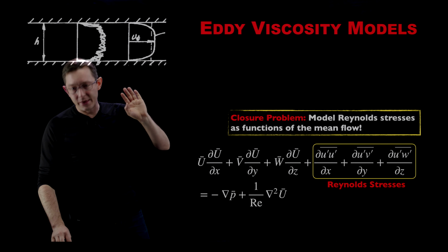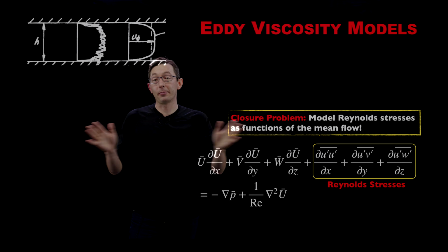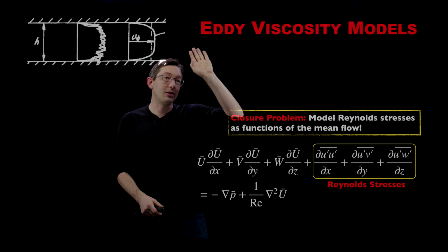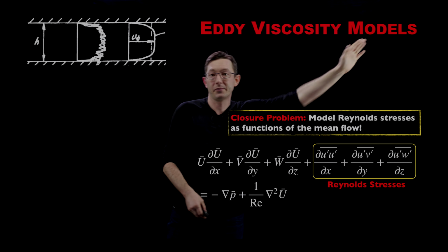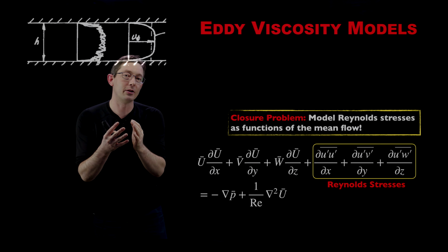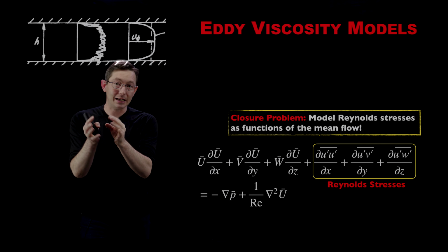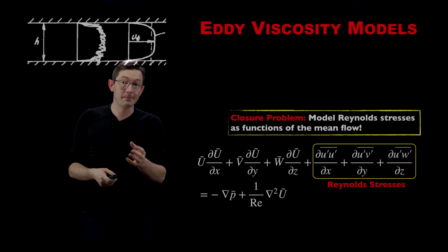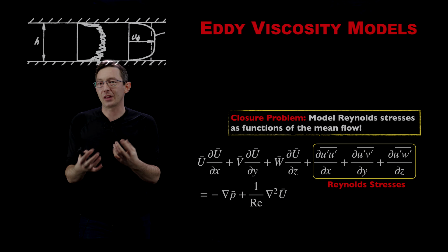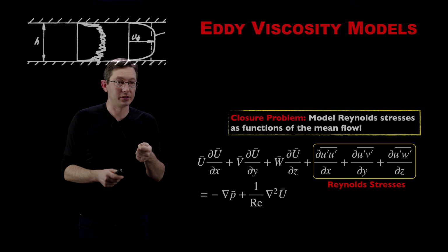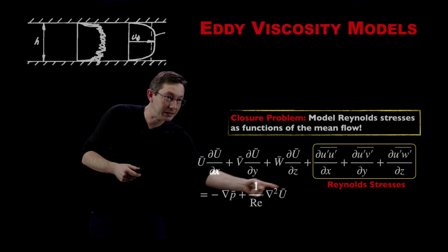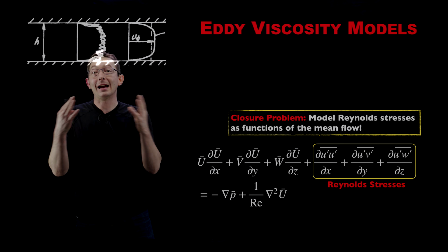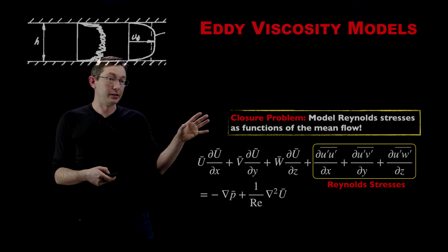And the simplest approach, actually the approach that people still take today, though this is an old approach, is called eddy viscosity modeling. So basically you're going to say that all of those tiny little turbulent scales that generate those Reynolds stresses basically act like viscosity in the Navier-Stokes equations. They act like this diffusion term here. And so we want to find the effective viscosity of the turbulence.